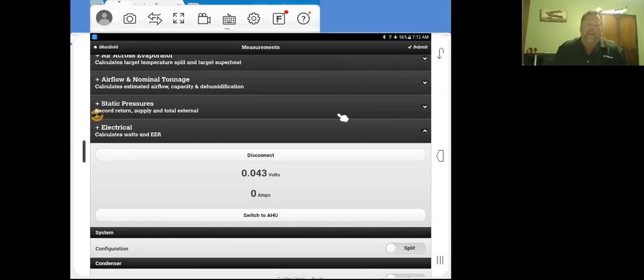Okay, perfect. So anyway, when you're using the DL429, and you can see it's very sensitive, and on my screen you'll see that there's a very slight amount of voltage jumping around there. It's very simple to zero it out. You just take your probe tips, just touch them together, and it'll zero itself out.